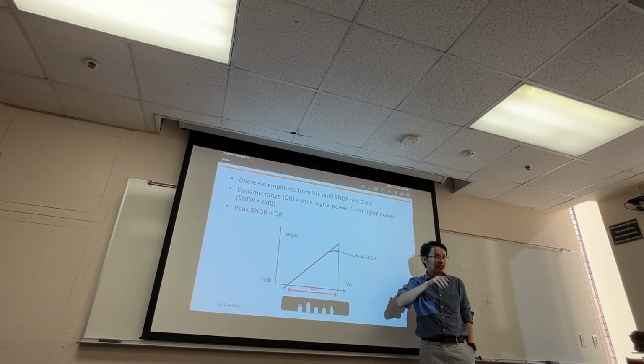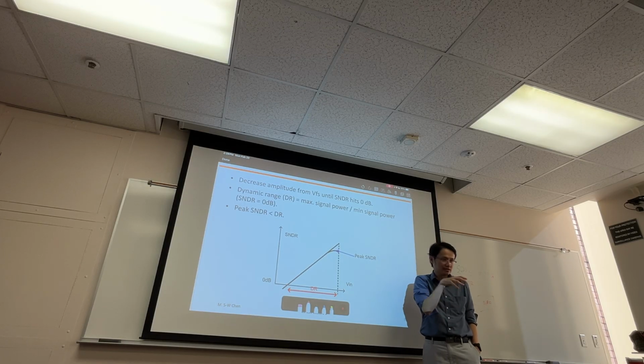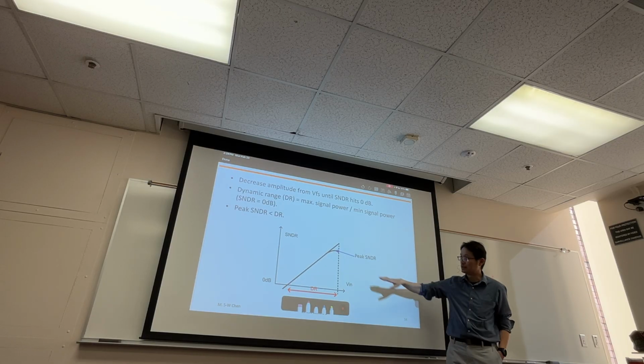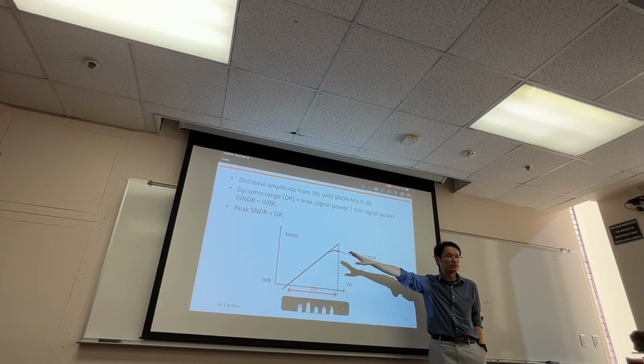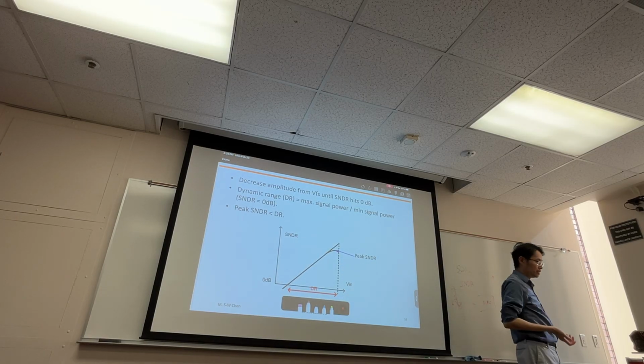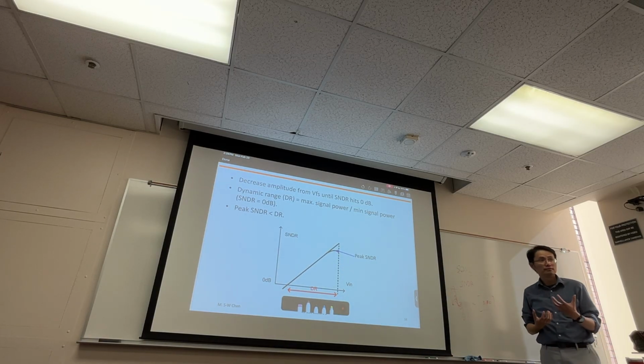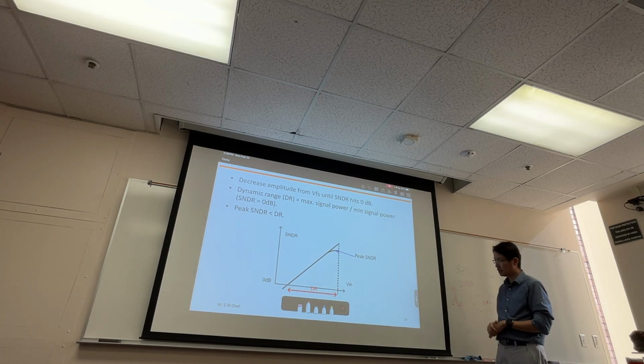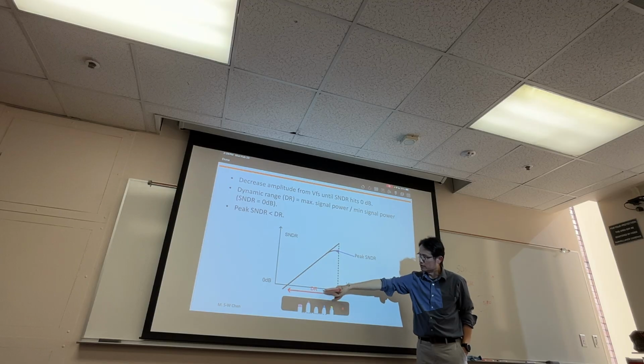If I look at SNR, probably it wouldn't go down as much, right? Because I only consider the noise for it, not so much the distortion, right? So you see different metrics will give you different information. But SNDR is always our ultimate measure, so if you measure that, it should give you the best. Okay. So then you start to define your so-called dynamic range.